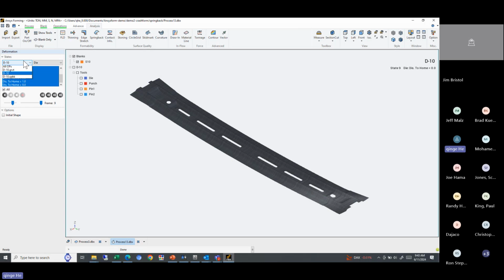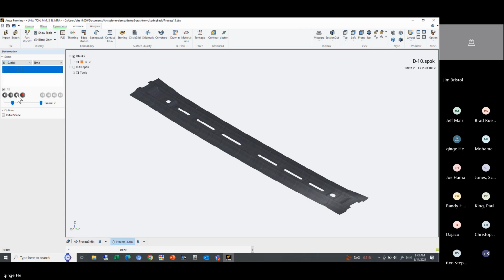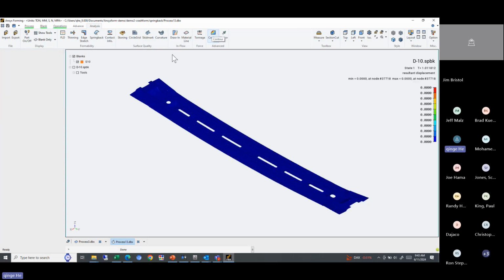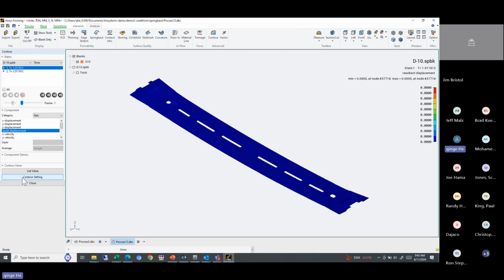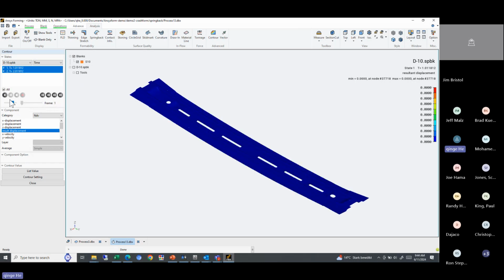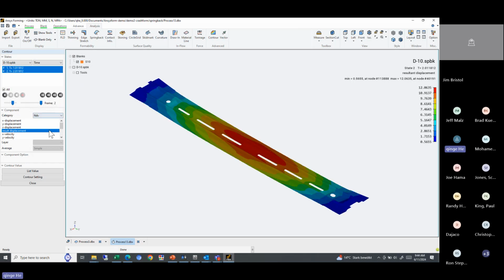Okay, and then now we can check spring back. This part of spring back is pretty high. We can check the amount. I normally use the same nodal value result. So we have 1/2 inch spring back, this area. Both ends didn't move too much, a little bit, but the center side spring back down like this.